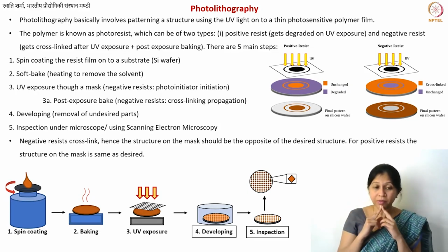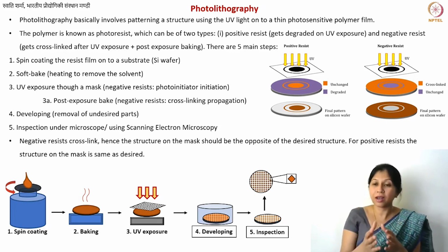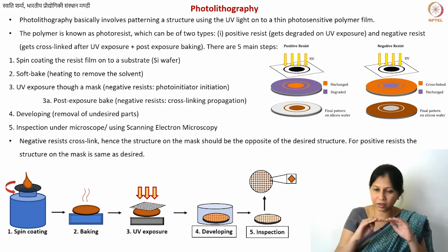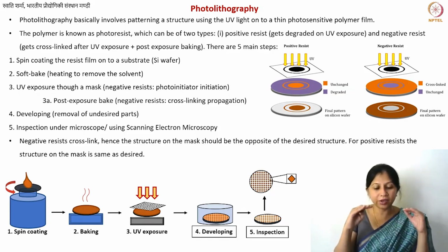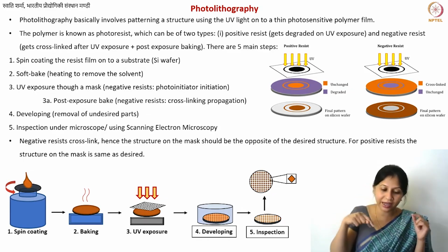Silicon oxide can be easily grown just by keeping the silicon wafer inside what is known as an oxidation furnace. So you have oxygen there and high temperature. The top layer of silicon itself converts into silicon oxide. The interesting part is that this oxide layer is electrically insulating.